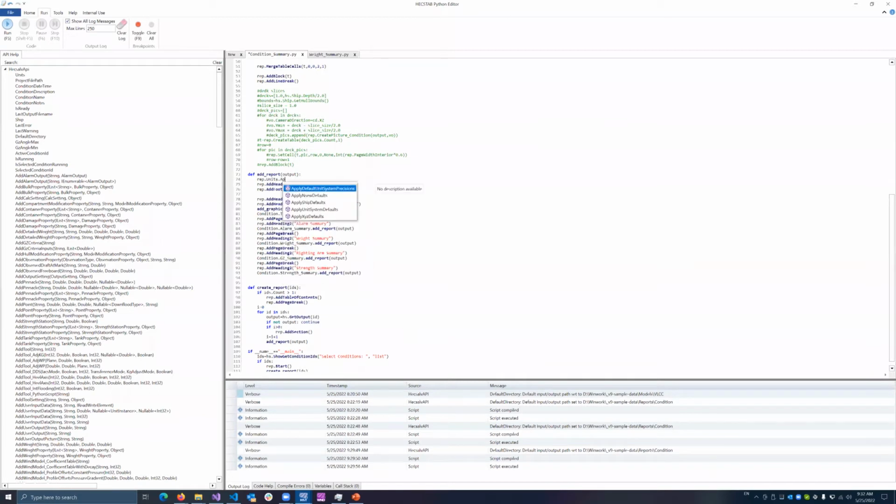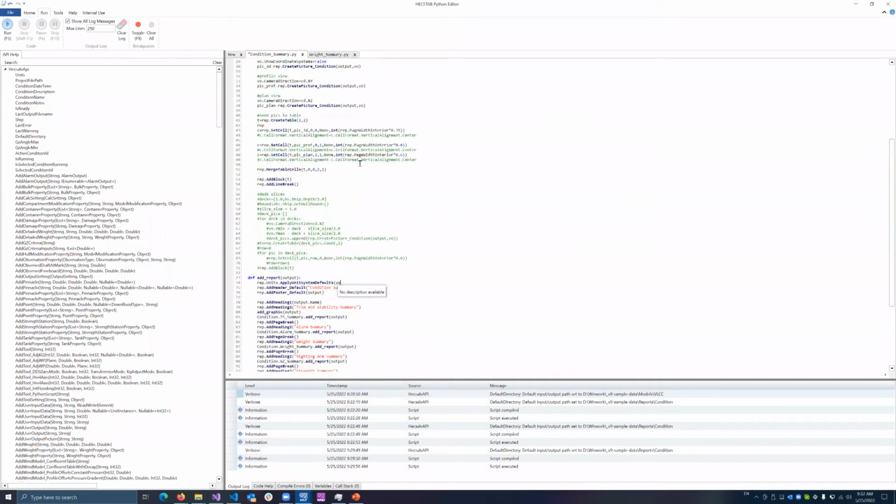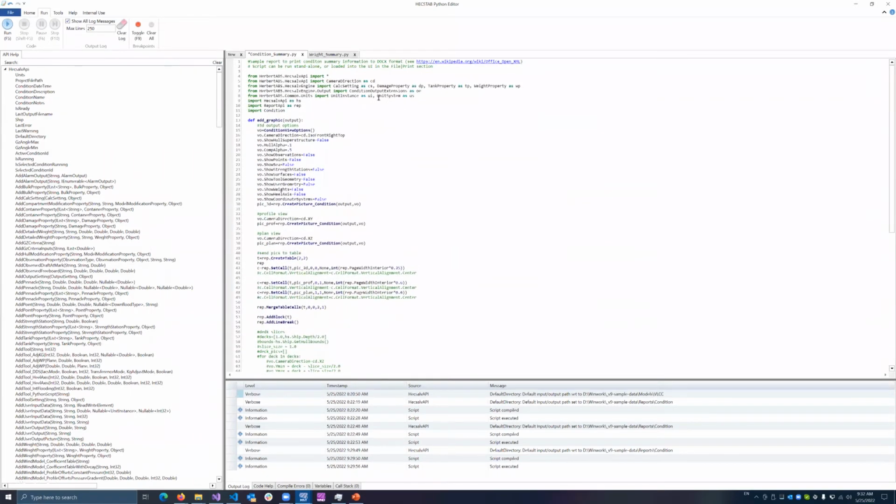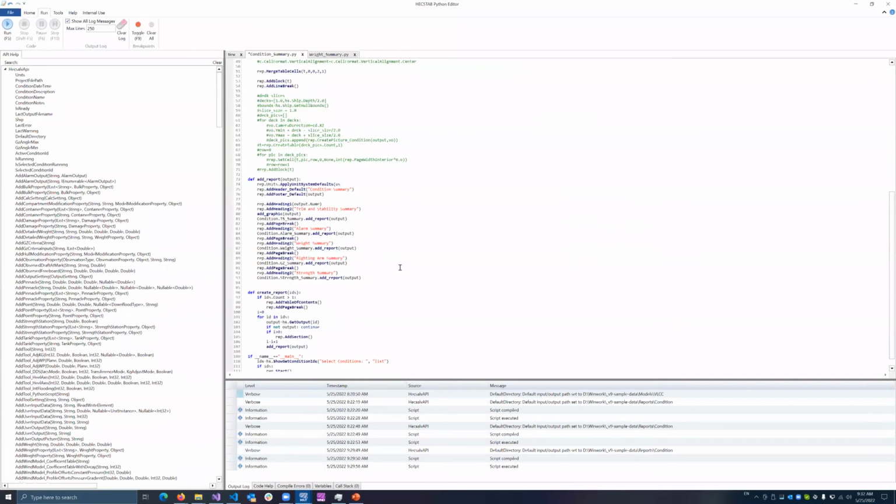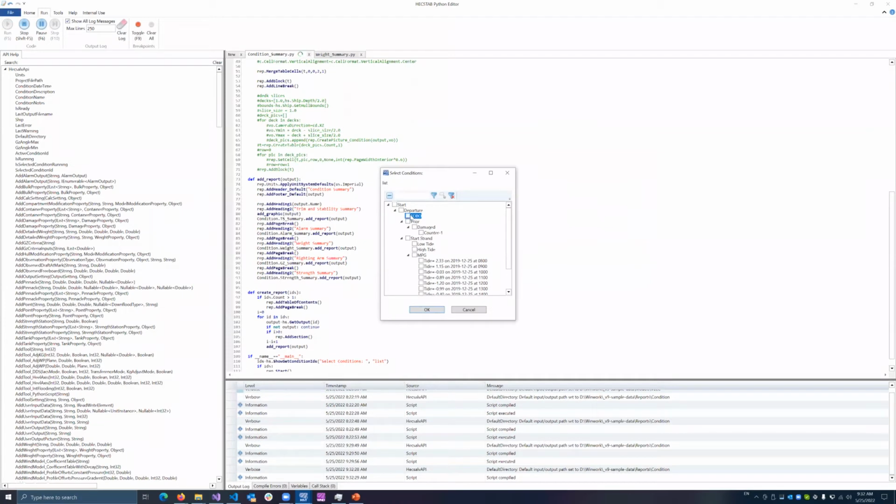And so I'll do this and I'll say apply unit system defaults. And I've brought in the way our unit system is set up. You need this unit system, and I've given a short name of US. Say US dot, I want just our general default imperial system. So now I can come in and run. It'll ask me to save.